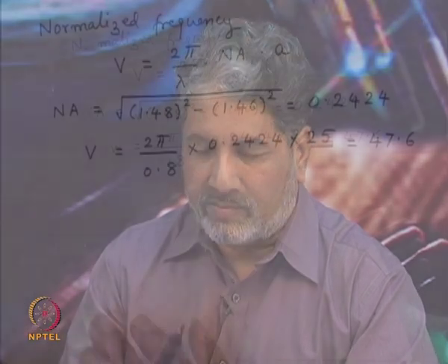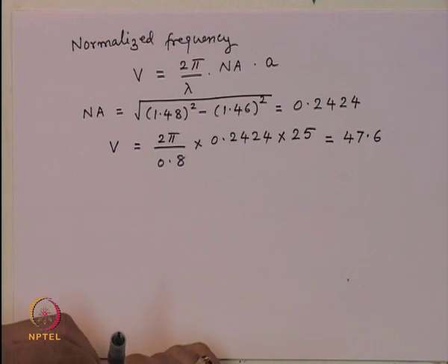And as we all know, on the optical fiber, the first mode which propagates is the HE11 mode. After that, a bunch of modes start propagating. The TE01 mode starts propagating, and at the same time the TM01 mode starts propagating, and that happens when the V number of the optical fiber is 2.4. So, the frequency at which the V number becomes equal to 2.4 is what is called the cutoff frequency of that particular mode.